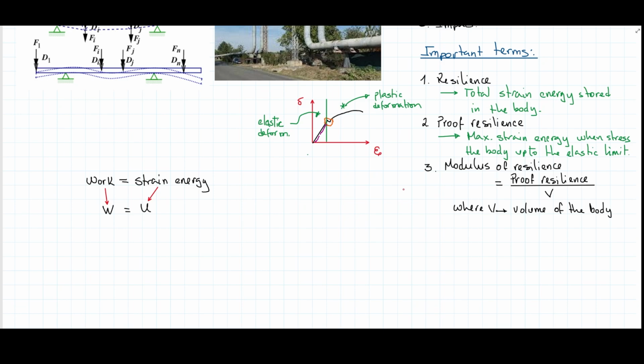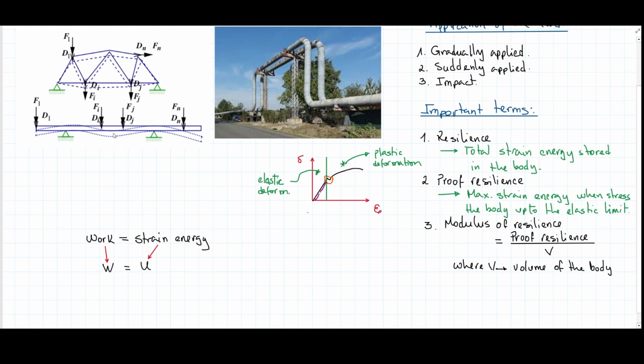So for example, if we want to know about the strain energy, let's start with work, because work is a better known concept for us during our studies up to today than strain energy. And work, as we know, is a relation between an applied force and the displacement that force causes. If we call deformation a displacement from a certain point to another, for example in this straight beam, if we pick a point on the top of the beam, and when you apply forces that point is displaced to the bottom, to this part here, then you could say that those forces caused work because they displaced a certain point.